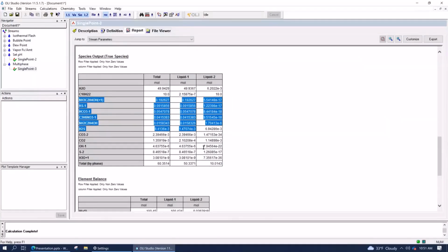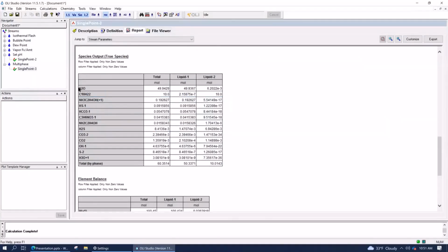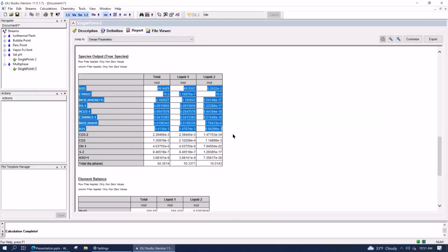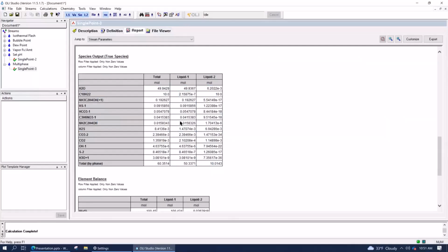Okay. Dino, I'm going to press on you again. What were you looking for, and do you see it here? And if you don't, let's talk about whether or not equilibrium models can actually calculate that. No, I do see it, AJ. I was looking for the N-reacted MEA, which I see in the element distribution under liquid 2, a minute amount there.